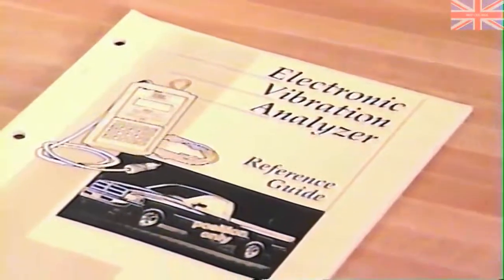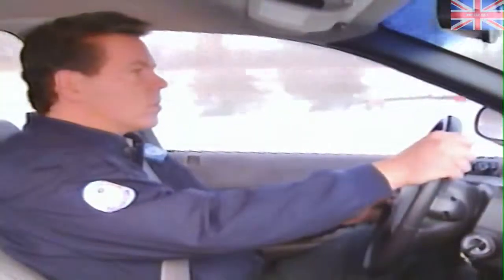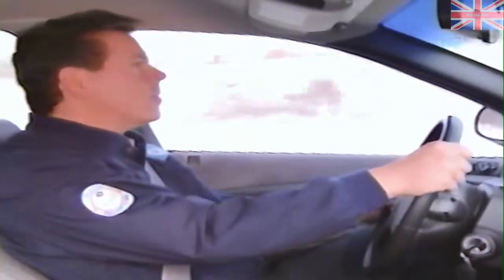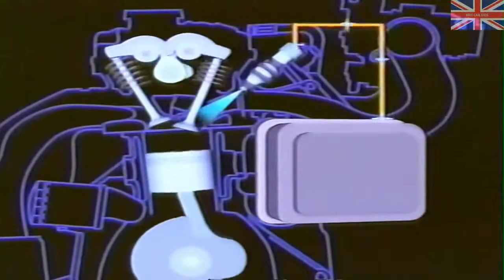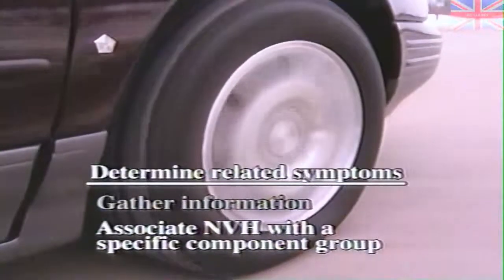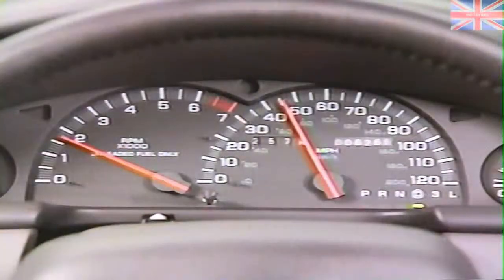Refer to the reference book included with the EVA for operating instructions. If you don't have an electronic vibration analyzer, you will have to rely on your senses to record noise and vibration frequencies. The second part of determining related symptoms is associating the noise, vibration, or harshness condition with a specific vehicle component group. Determining whether the noise or vibration is associated with engine speed components or vehicle speed components is the first and most important association.